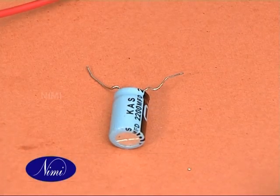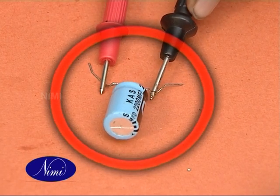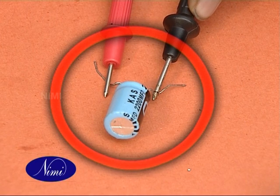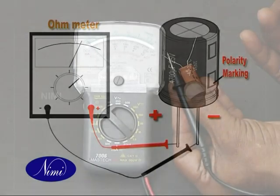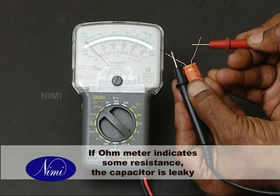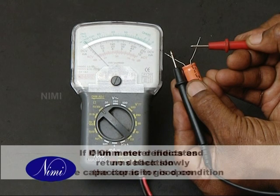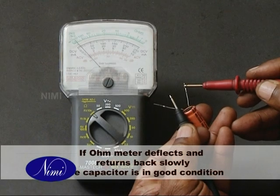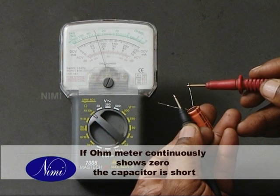While testing a polarized capacitor, the positive terminal of the capacitor is to be connected to the positive terminal of the ohmmeter and the negative terminal to the negative terminal of the ohmmeter. If the ohmmeter indicates some resistance, there is some leakage. No deflection: open. Deflects and returns back slowly: capacitor in good condition. Continuously shows 0 reading: short.